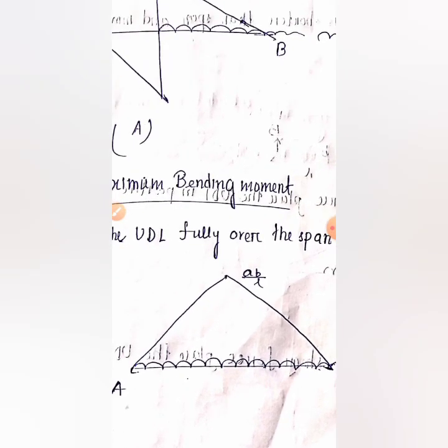Now we want to find the maximum bending moment. Just read the question. We have to find the maximum bending moment, not absolute. Okay. So suppose at section C we want to find the maximum bending moment. So we'll draw it, and the section C is at some distance from the left support A. So the coefficient or the ordinate value of bending moment is what? AB by L. We have discussed it earlier.